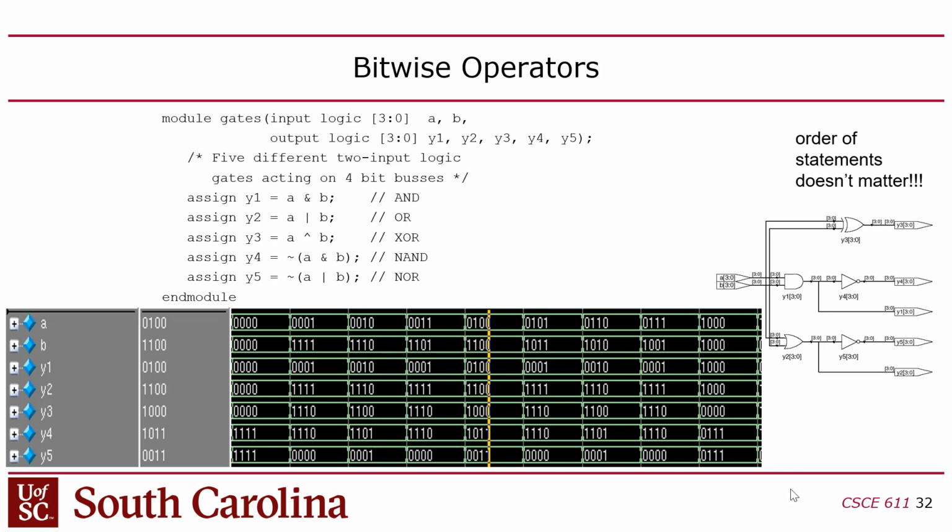Okay, so also I mentioned this logic type. If any of you have seen Verilog before, logic is the type in SystemVerilog that has replaced the wire and reg types in Verilog, right? So logic basically just means it's a bit, but it's a four-state bit that includes the X and the Z values that are used for simulation purposes, right?